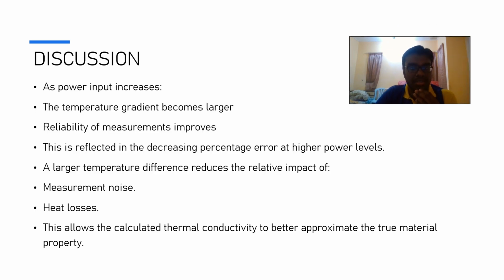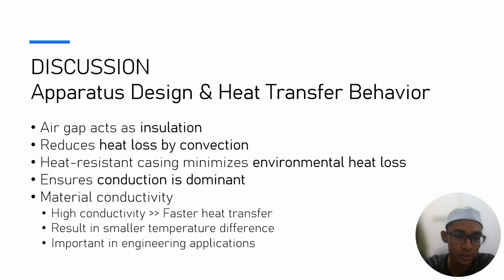As power input increases, the temperature gradient becomes larger. This improves measurement reliability and the percentage error decreases. Larger temperature differences reduce the impact of noise and heat loss, so the calculated conductivity gets closer to the true material property. Discussion on apparatus design and heat transfer behavior.